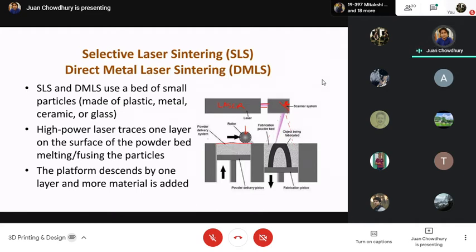Now the roller will start its motion and it will displace the material into the fabricating piston. Okay, and the moment it does, the fabricating piston will move down. This displacement will cause one layer after another to be melted, and eventually you'll form the parts. Again, because the solid material is already available in this space, you don't need to create any supports. But then you would need the whole amount of the work volume of the material that you are printing. I was talking about it yesterday.